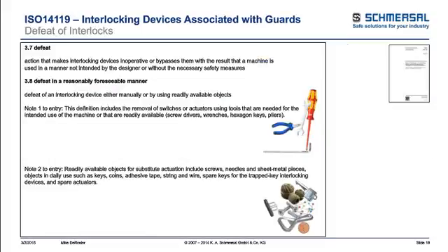So as a result of those studies, they have added some verbiage in the ISO 14119 standard, and they were defining what defeat is, as well as defeat in a reasonable manner. And what does that mean? When you look at what's highlighted there, defeat makes interlocking devices inoperative or bypasses them. The defeat in a reasonable, foreseeable manner, whether you're manually or using readily available objects, such as tools.